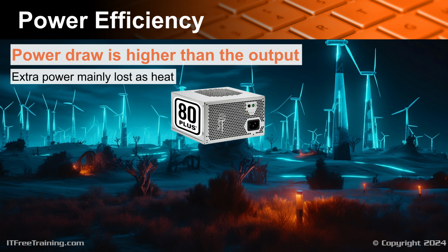This power supply is marked as 80+. 80+ is a voluntary certification program intended to promote efficient energy use. The lowest option is just 80+. Higher certifications are marked as bronze, silver, gold, etc. As the rating goes up, the power efficiency goes up. In this example, the power efficiency is 80%.